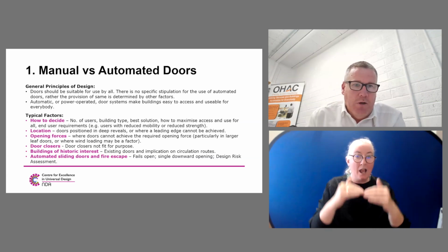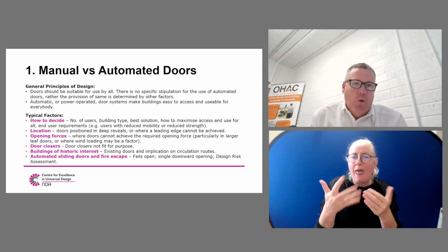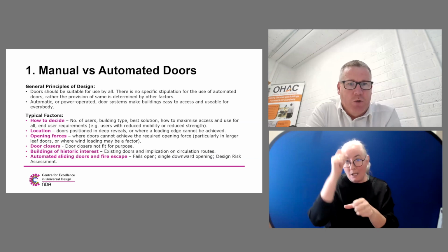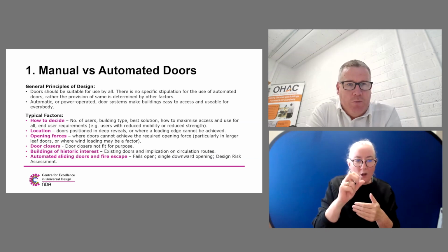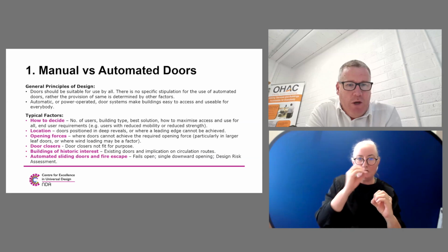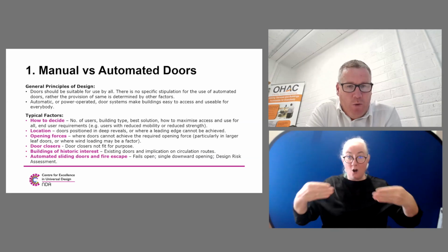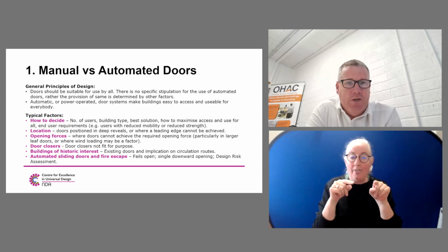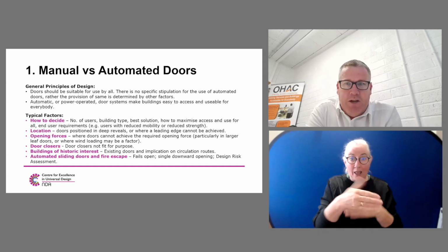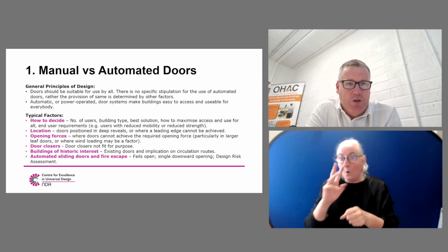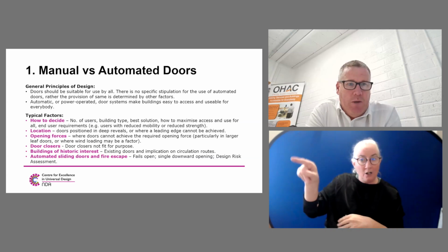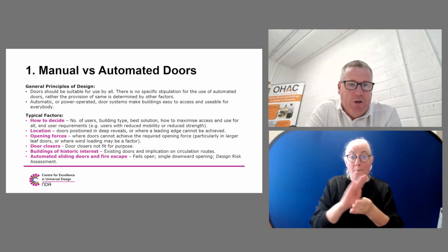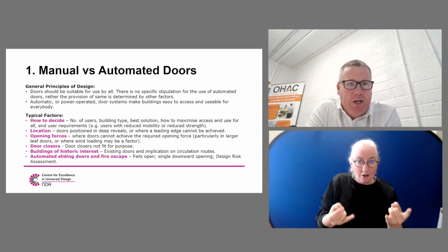Opening forces. We found on a lot of projects, when we started our role as ancillary certifier, that you needed to factor in the opening forces of the door: 30 newtons or less opening force from 0 degrees of the opening cycle. If you have larger doors, such as a 1 meter wide effective clear width door which is fully glazed, it may be a heavy door, and you also need to factor in wind loads and different weather conditions at your building. It became apparent from very early on that as the door gets wider and heavier, you may need to look at automating the door.